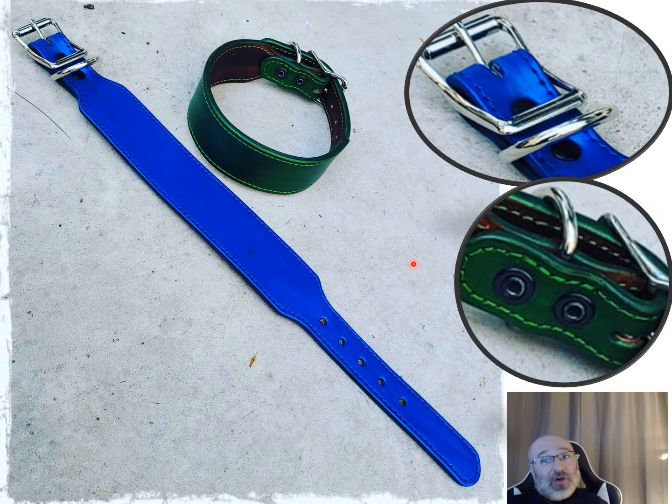You don't roll it over enough and all of a sudden you can pop a rivet, even one of these industrial strength ones. So you got to make sure you have the right pressure to get the right amount of rollover, which is a calculation within itself. So you can see on the inside right there, there are the washers with the rollover from the tubular rivet. And what you can see here is on these, I have a solid stainless steel D-ring, which the leash attaches to. So when the leash attaches to that, you're pulling on that. So this here almost does pull these guys right into tension when you're pulling up on this D-ring, coming out with that force there.